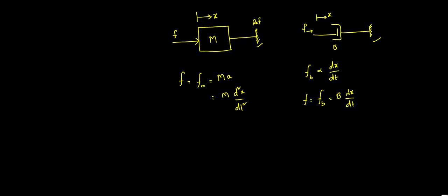Now, suppose the dashpot is not connected anywhere, and there is displacement at both ends. Say, for example, here this is the case. I am considering the dashpot here, and instead of fixing it to a certain reference, it is just left free. So when you apply a certain amount of force F here, it may displace by a distance x1, and here also it is not connected to anything, so it may displace by a distance x2.